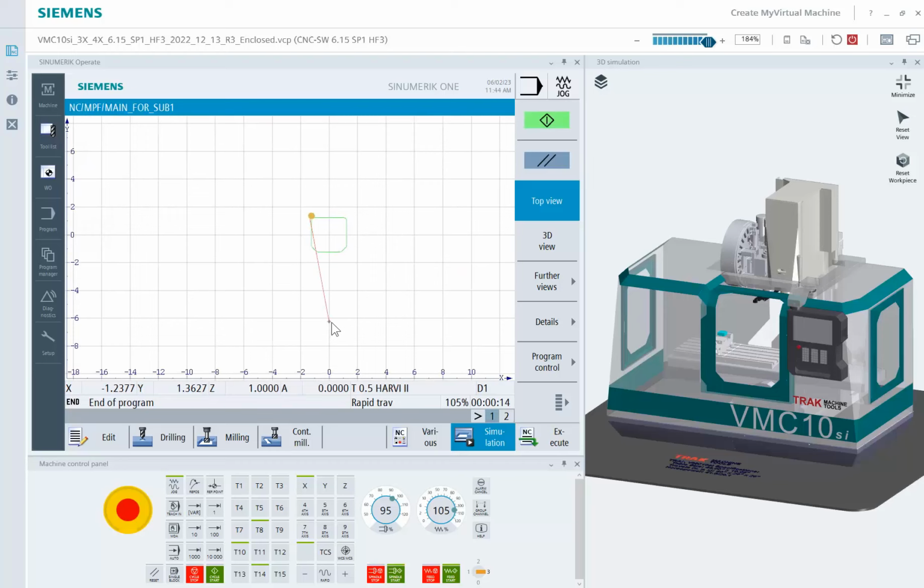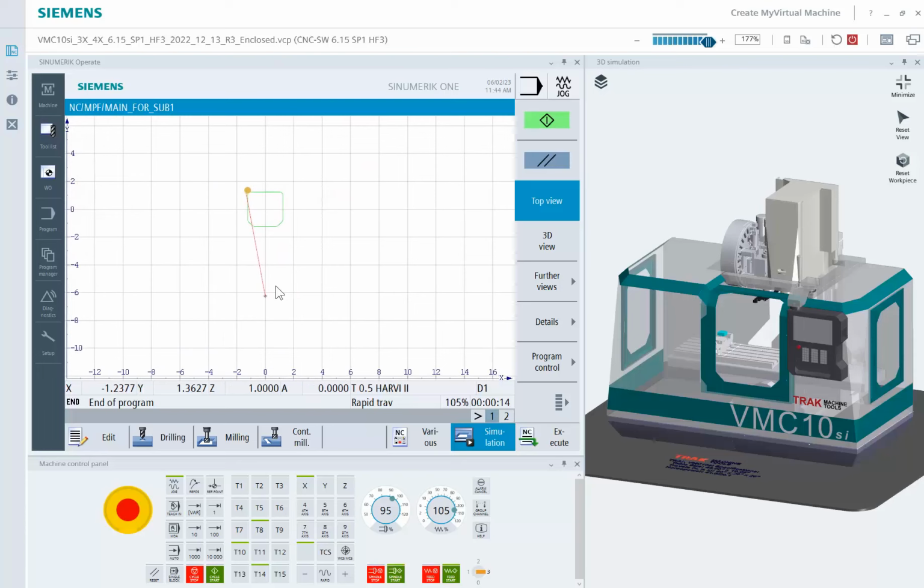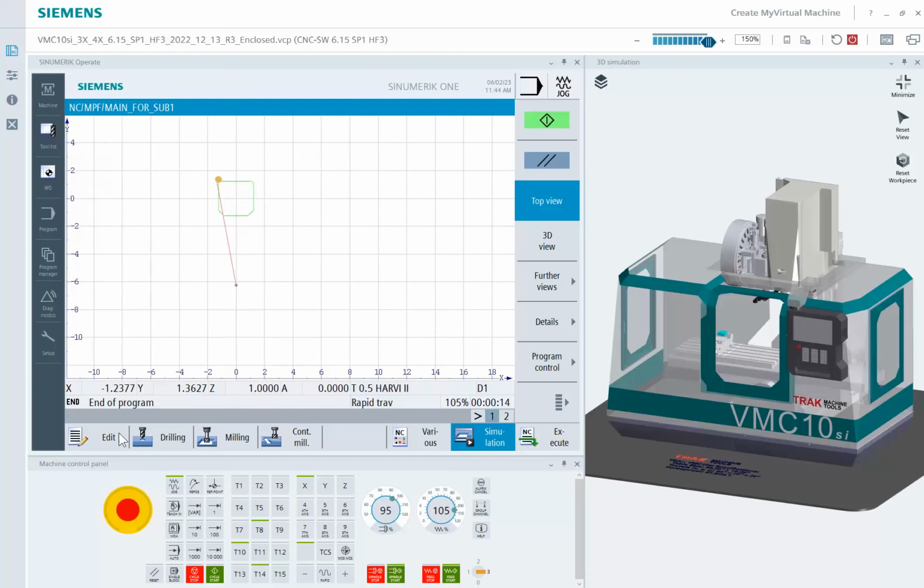Yeah, so that would be my 0 location that I'm coming from now that I have no G54. So that looks about right. I would buy that. Okay. The other thing I could have done is put an initial feature of some form just to get kind of my baseline for graphics. Sometimes we'll update the graphics based on at least the 0, based on where I'm shifting my zeros around. So everything looks okay. I think I'm all right. Let's continue on. Really where we'll see it is once we try to go to mirror it, if I'm not shifted properly.